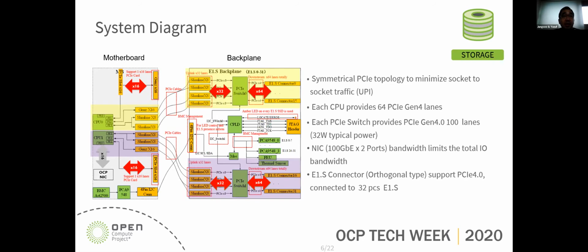So this is a system diagram, and it shows the PCI topology of a Poseidon system. Since Poseidon OS recognizes the NUMA architecture, the topology is designed symmetrically to minimize latency and offer stable I/O. As you can see, each SSD is connected with 4 lanes to maximize single SSD performance, and a total of 16 SSDs are connected to each PCI switch.